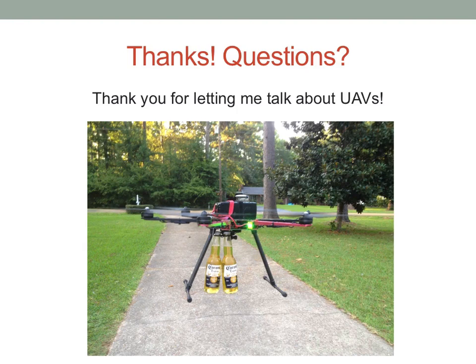What you would do is you could fly lower, maybe at like 100 feet. But what you're doing is you're taking a series of pictures, and then when you get back, you're mosaicing all those pictures together to create one big picture of the whole area. That way you can fly lower, get really high resolution individual images, and then when you mosaic them all together, you have that one big picture of the whole track. Now you could fly up to an altitude where you can get the whole track in one picture, but then your resolution has suffered and you can't see all the detail that you'd want.